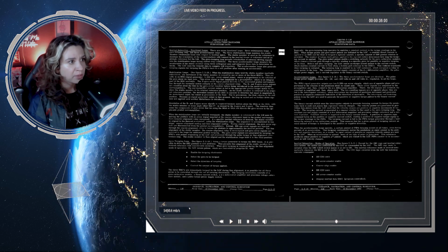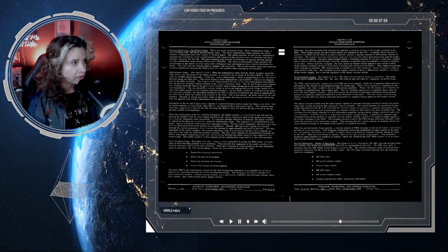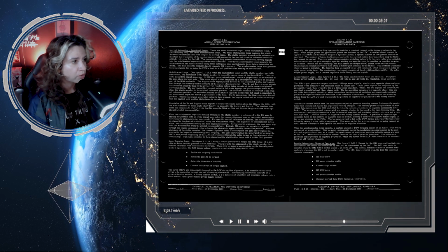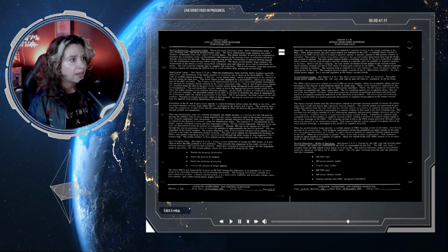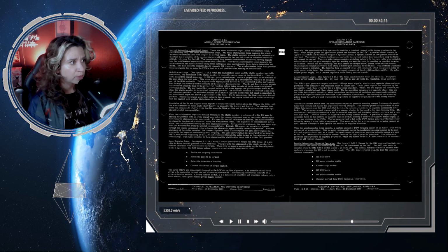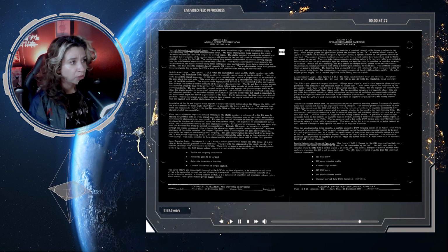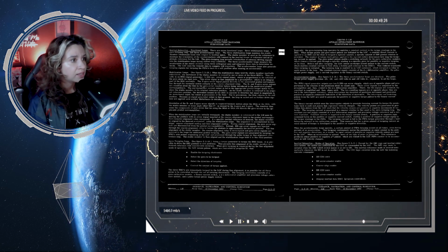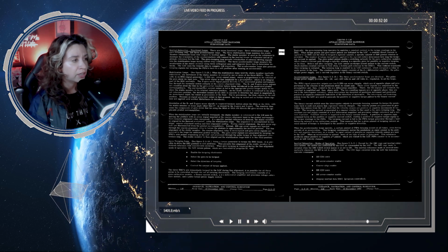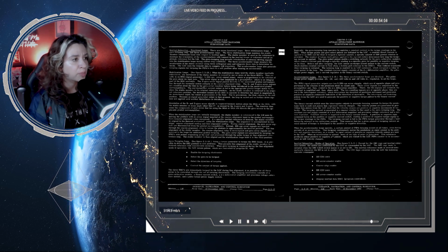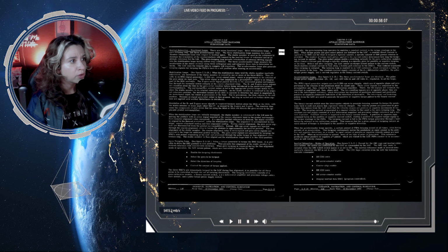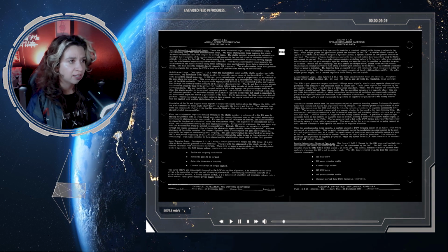The 3 accelerometer loops measure the acceleration of the stable member along 3 orthogonal axes and integrate these data to determine velocity. The LGC uses the velocity data to compute LM trajectory. The accelerometer loops also generate torquing signals for torquing the PIPAs back to a null position after sensing an acceleration.